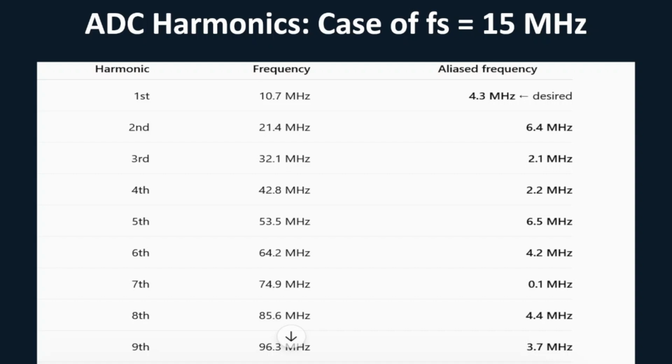So again, the designer here, when he or she decides to start using bandpass sampling, you'd have to be careful about these challenges. The first challenge is making sure you have enough margin so that you can design a flexible anti-aliasing filter. You don't want to have tones that could alias into your passband, and you want to have flexibility designing a cheaper anti-aliasing bandpass filter.